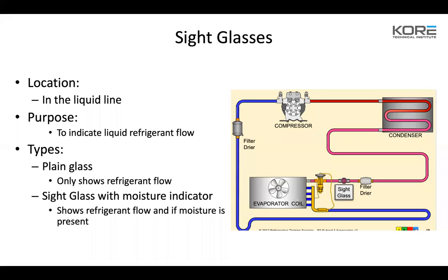So what do we want to see in the sight glass? Smooth flow. Clear full, right? I hear clear, and then the first thing I ask a guy when he calls me is, clear full or clear empty? Well, a couple times you come up on bigger systems with sight glasses and it looks full, but if you shine your light down in it, you can see a river flowing down in the very bottom of the sight glass.